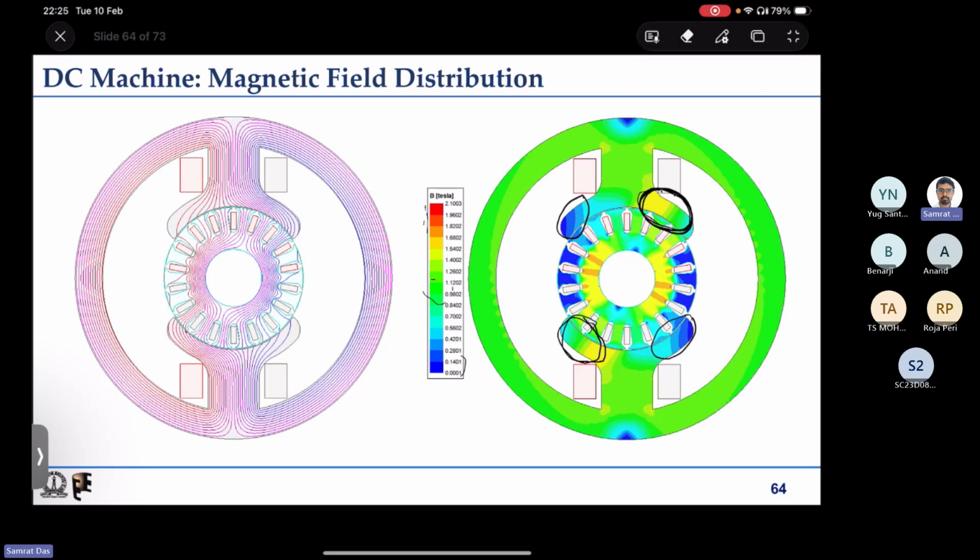So this we will see step by step for the DC machine, because if we understand one case, it's the same thing: two fields producing some resultant field. We will see that one field does not produce any torque. The second field on its own does not produce any torque, but the two fields, because there is some resultant field, will produce some net torque. How that happens, we'll look at step by step for the DC machine.